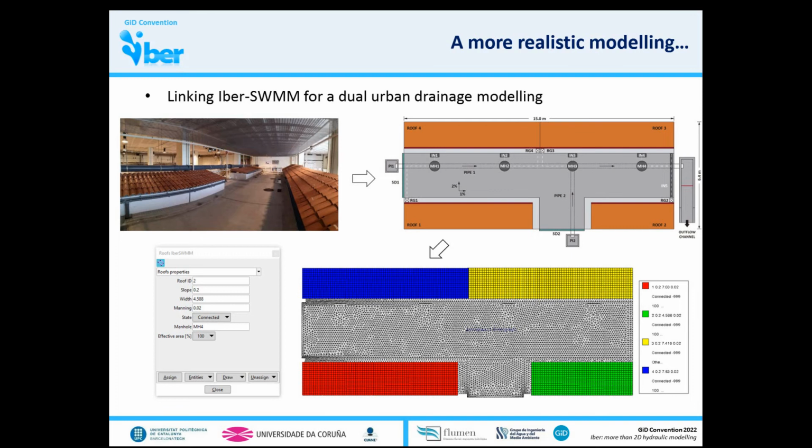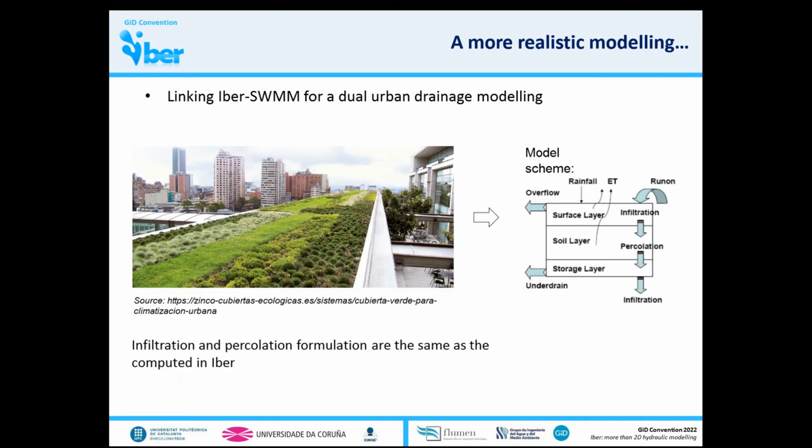The development of a high-resolution model of pluvial flooding with Iber-SWMM implies the definition of roofs in the urban areas, since their areas and their effects cannot be ignored. Thus, a new dialog is created to define and assign the roof parameters over the surface in one step. Physical parameters of roofs and their connection with the network and the treatment of their discharges must be defined.